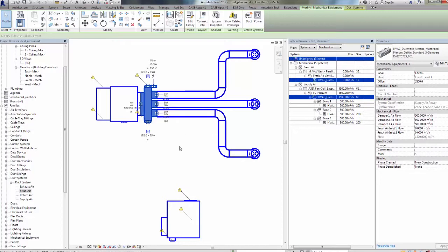Then, the fresh air flow is being specified directly on the plenum. Supposing there's 200 cubic meters per hour fresh air from connection 2, we see how the indoor unit global airflow is adapted to 1300 cubic meters per hour. Now we make the connection for the fresh air unit to the plenum by means of a duct.